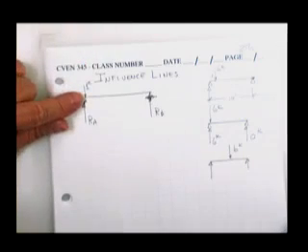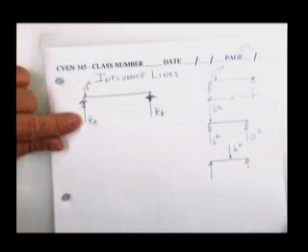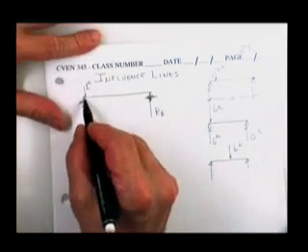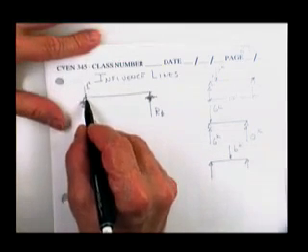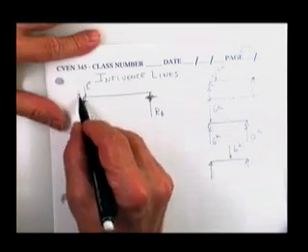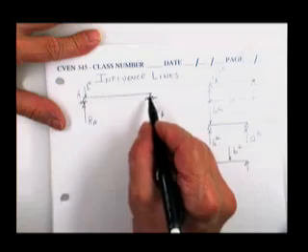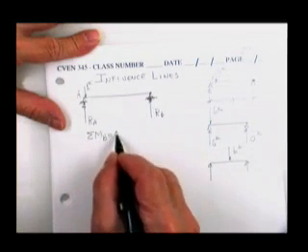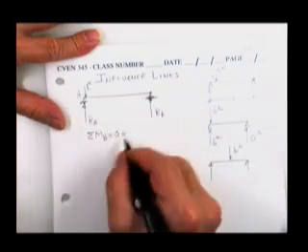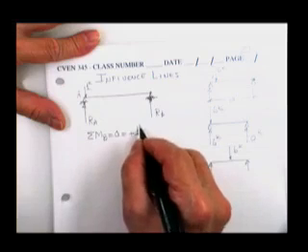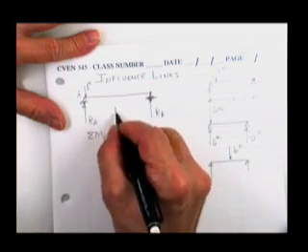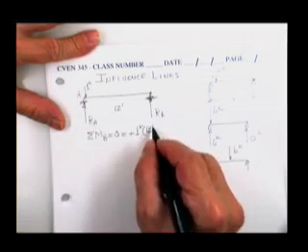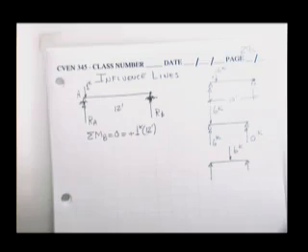Now, first off, the load is off of the span, and the reaction at A is 0. Then, when I put the load just a little bit to the right of point A, I sum moments about B is equal to 0 is equal to plus a 1 kip load multiplied times his moment arm. This is a 12-foot beam that I'm generating the influence diagram for the reaction at A.